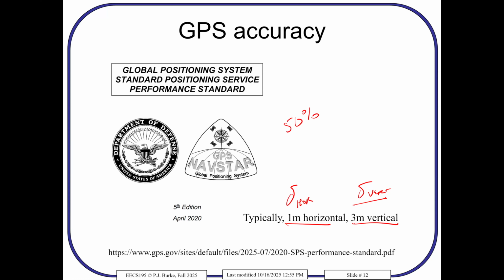And the vertical is also difficult. So the vertical is worse because 3 meters, that's the height of the cage, so that means almost all the time your height is not known. So what is the solution for that in our class that you already have? Barometer, yeah. So you don't have to just rely on GPS. The barometer on the flight controller measures the pressure of the air, and that determines your relative altitude relative to takeoff.